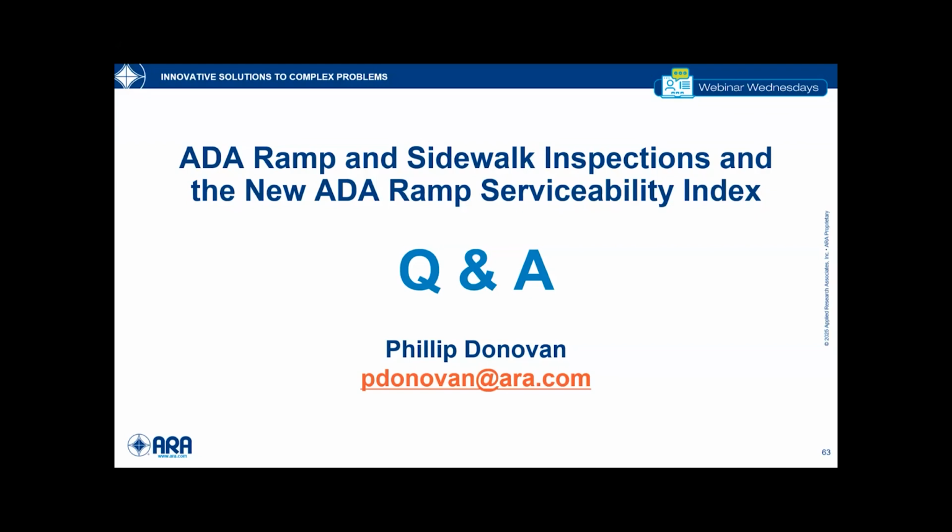There was a comment or a question online from Chris when you mentioned the LiDAR detection. Can you strap the phone to a Segway or some other mobile device while doing the LiDAR survey? Yeah, whatever you can strap it to, whether it's a person or a bike. The key thing is the speed of data collection and where that device is at. So yes, you could put it on a Segway and you could put it on a bike, but it's got to be level and it's got to go very slow. It's a very slow process.